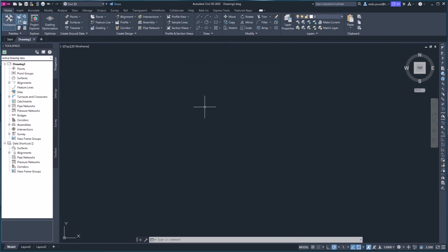As I mentioned, Civil 3D can be also used as AutoCAD. For that, to be able to use just AutoCAD-based toolset, you simply select from the top left corner Drafting & Annotation if you want to create 2D drawings, 3D Modeling if you want to create AutoCAD 3D drawings, and Planning and Analysis if you are a GIS expert.